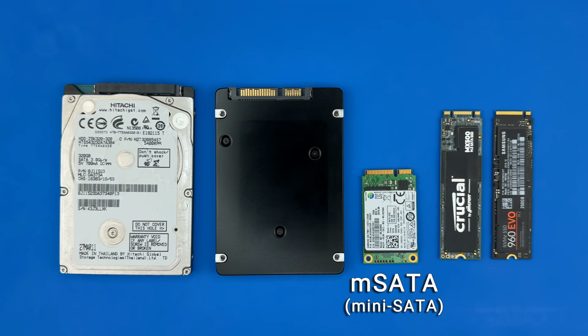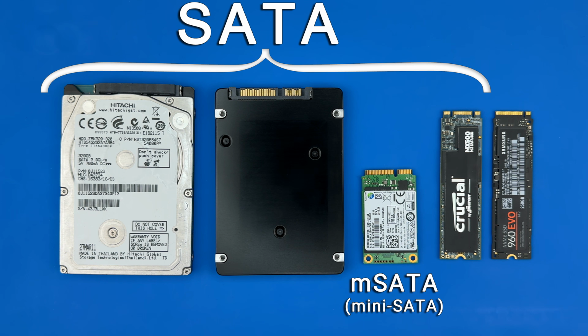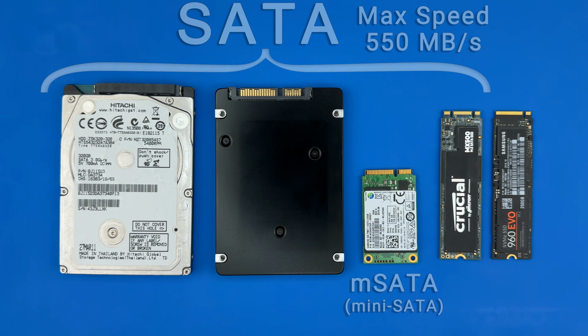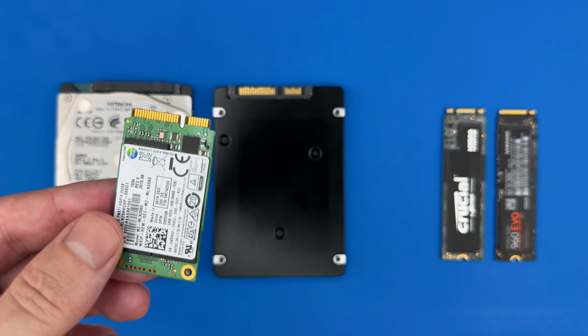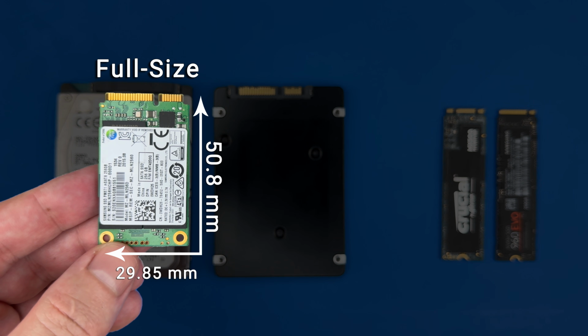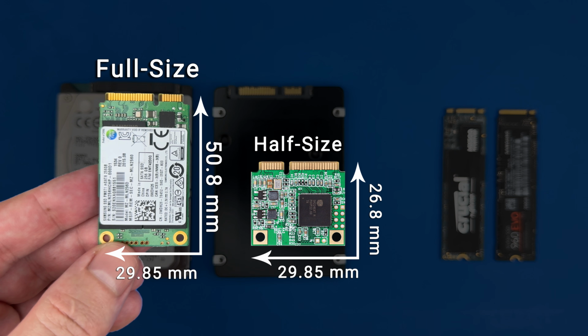mSATA SSD is a compact version of the SATA SSD, designed for use in small devices such as laptops, ultrabooks, and embedded systems. It offers the same performance as a standard SATA SSD, with speeds limited to approximately 550 megabytes per second, but in a smaller form factor. mSATA SSDs are available in 2 sizes, full size and the less common half size.